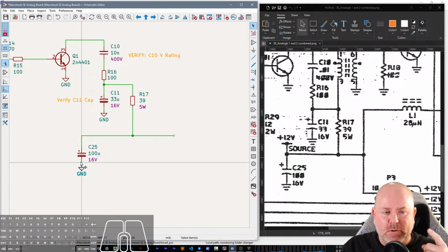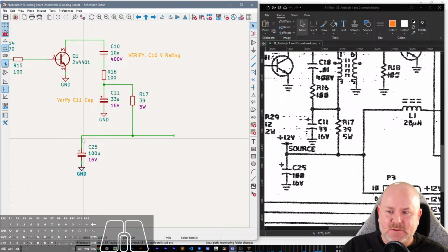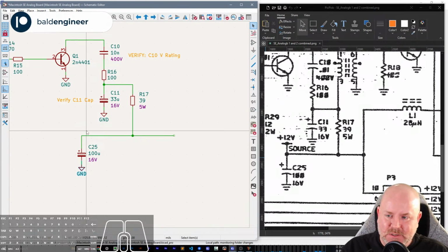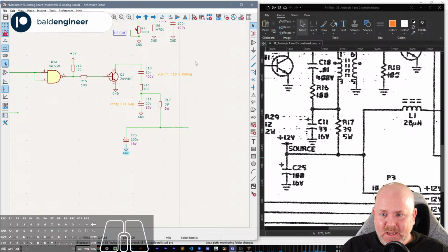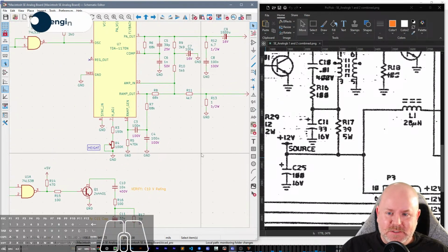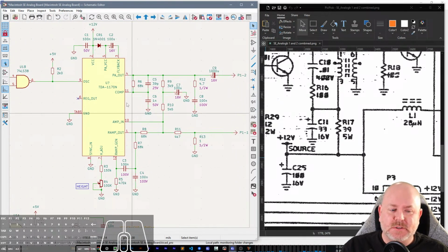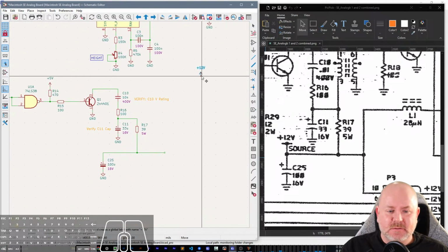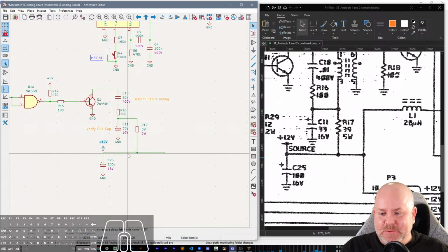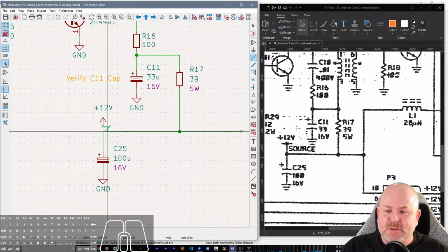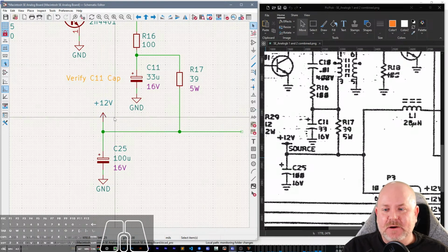I'd give them a polarized and a non-polarized capacitor, a couple of resistors, and LEDs. I would hold up a resistor and ask people, what value is this resistor? People would start looking at it, and usually somebody in the class would know the resistor color code, and I'd say, guys, you have a test tool to measure the resistor. Just measure it. It's good to know the color code, and it's not a bad idea to double check, but it was a trick question.